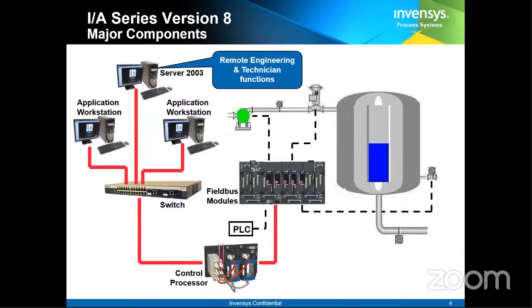If it is purely a switch, let us say a pressure limit switch, then you simply need a digital input module. The limit switch will provide either 24 volts or 0 volts, so in that case you will have a digital input module.